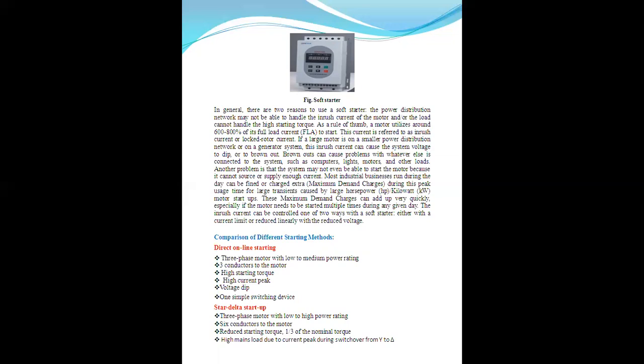That can cause problems for whatever else is connected to the system, such as computers, lights, motors, and other loads. Another problem is that the system may not even be able to start the motor because it cannot source or supply enough current.